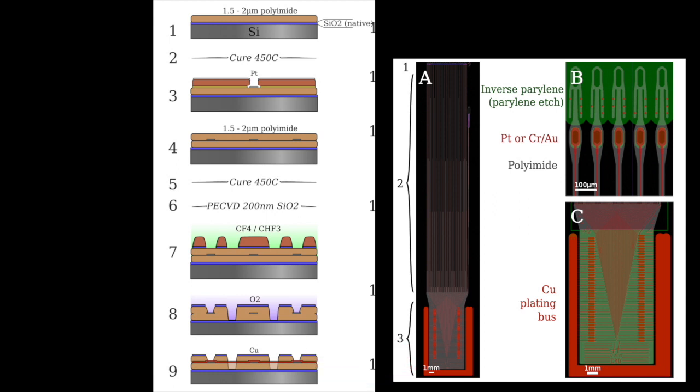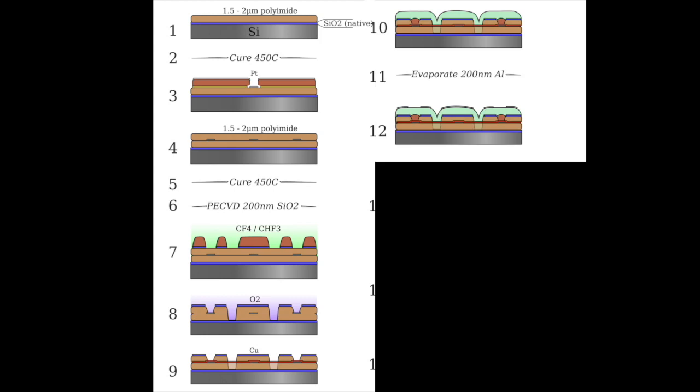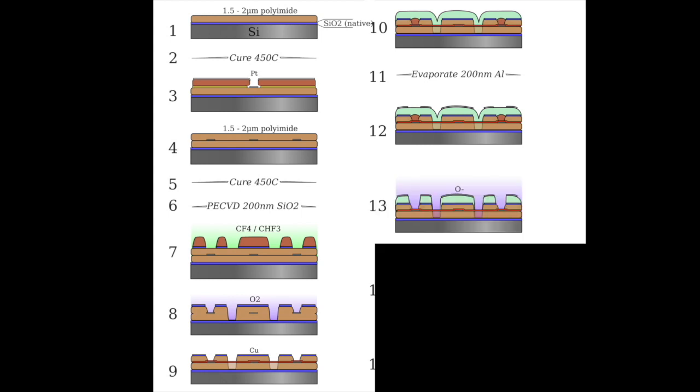Okay, the next step is to deposit and shape a thin protective barrier around those existing structures. A polymer called parylene is used. Unlike polyamide, which requires spin deposition, parylene can be deposited using evaporation. It's less of a flexible polymer and doesn't have as much heat and chemical resistance as the polyamides, but it does protect against moisture damage. The parylene is evaporated onto the board, followed by patterning an aluminum hard mask on top of it. The sections of the parylene that are unprotected by aluminum are then removed using oxygen plasma.